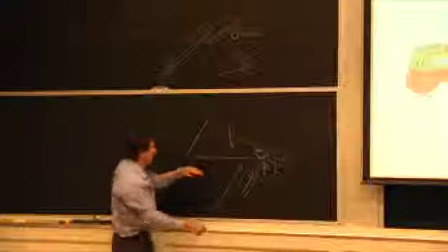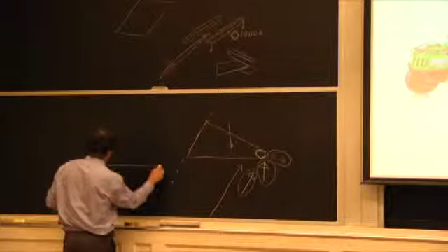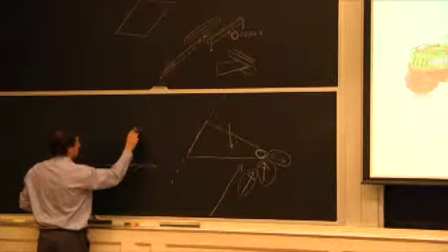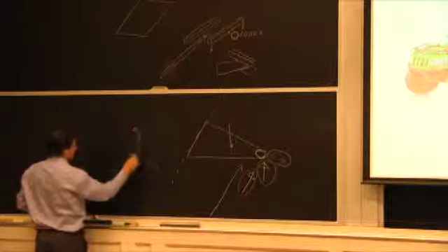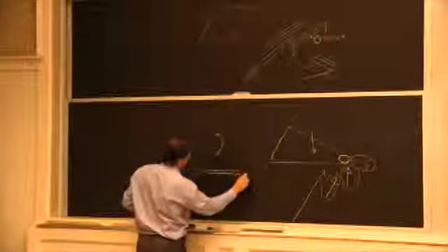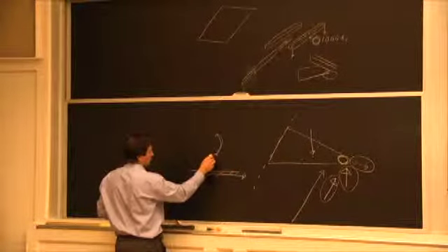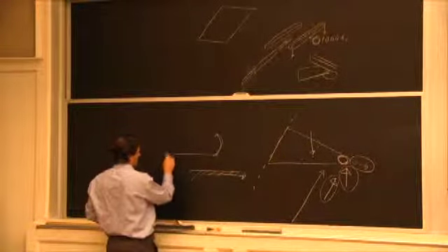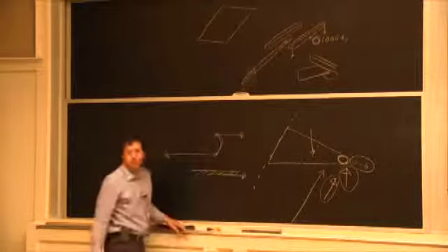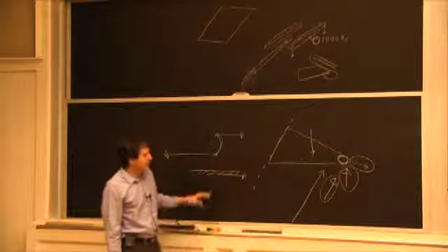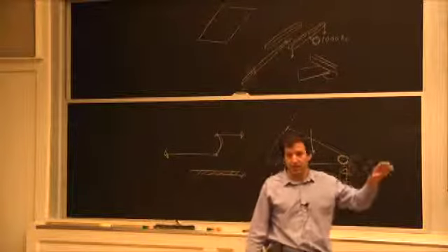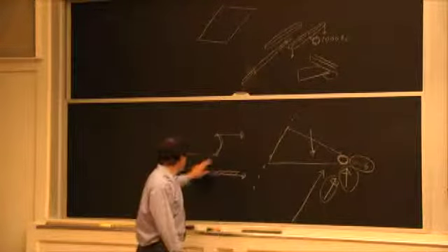because when you're further from the ground, you don't have as much of that back and forth force. If we're looking, this is the ground. You have the two ball joints, and that's the knuckle. So the force ultimately comes from the ground, say, backward. What this ball joint needs to do is to resist it by about twice as much, and then you reach equilibrium with about half the load on the upper one. And that actually shows up in that design. It doesn't really come from testing. It comes from that simple analysis of moment.